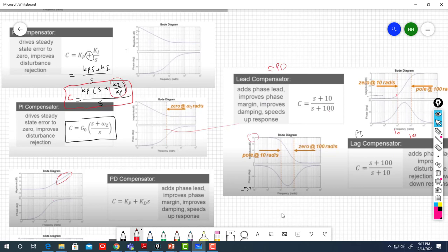But PD is still not the case because of the noise and so on, so it is better to add a low pass filter. So the lead compensator is used in the case of PD, and PI is better than a lag compensator. But you can still add lag if you want more computational efficiency and less energy consumption if it's an analog implementation.